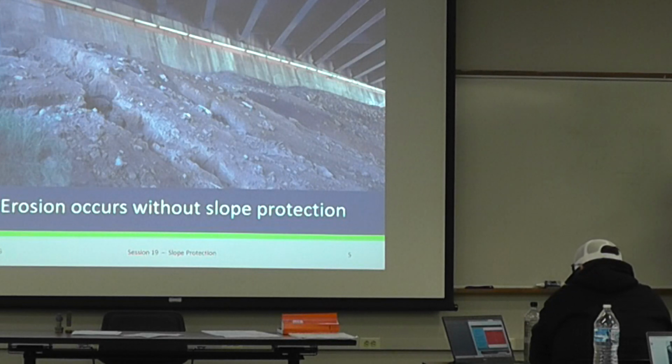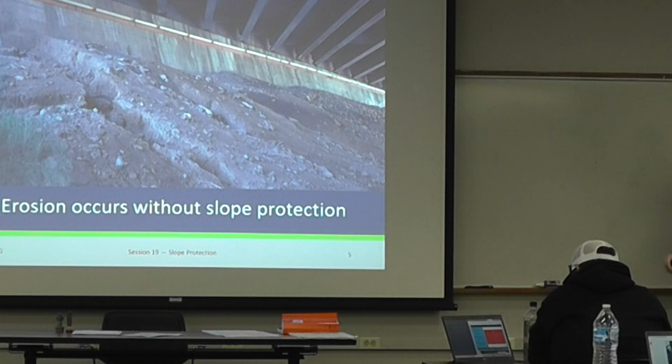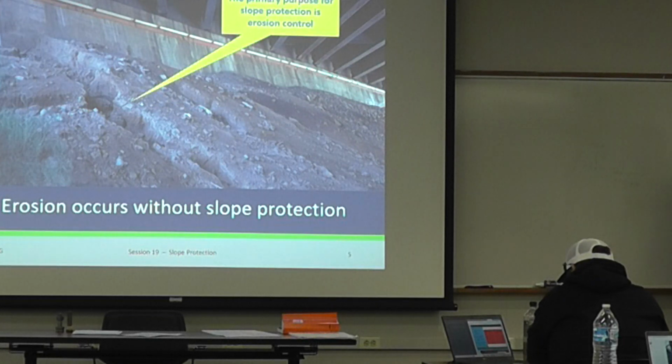Dwayne, isn't it like 7 days soils can remain uncovered? Yep, depends on where it drains to, but yes. So, a long time ago, this was left uncovered. They blew it. That's something we want to get after sooner than later. So again, the primary purpose of slope protection is erosion control.